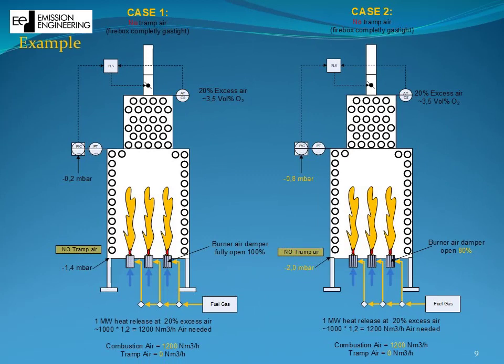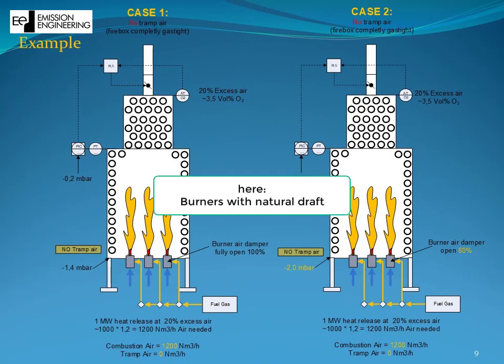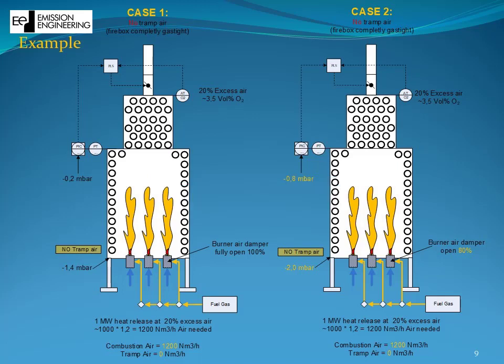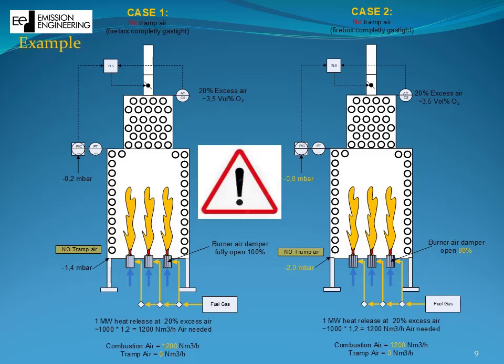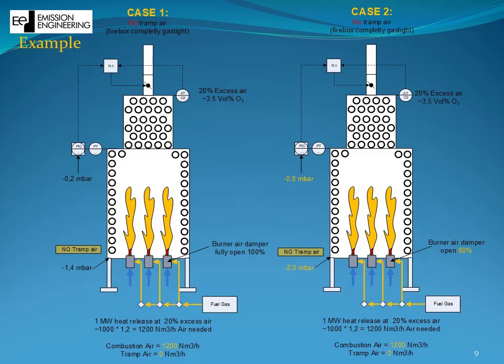As fired heaters change their heat demand more often, some end users came to the conclusion that they are going to implement an automatic control loop, using draft and O2 content in the flue gas, to sustain their operation without a need for field operators adjusting the burner air dampers. But this can be dangerous, specifically if you want to operate at low excess air levels, like for example 10% and lower, at all times due to efficiency reasons. We will explain to you also why.